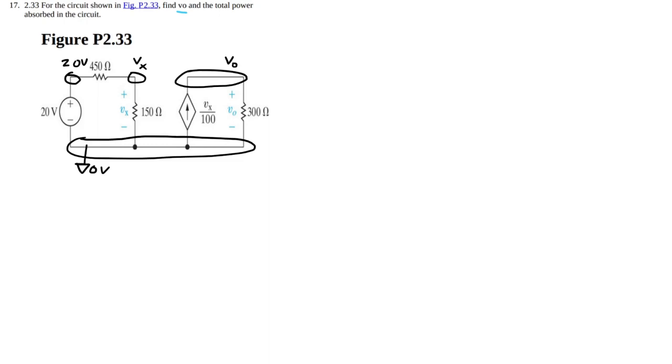There's a lot of different ways to do this. The easiest one would be to use the voltage divider equation, which, if you're unfamiliar, is your voltage output equals your voltage input times the ratio of the bottom leg of the voltage divider over the total. Now, it's not written like that in this circuit, but let me draw a voltage divider real quick.